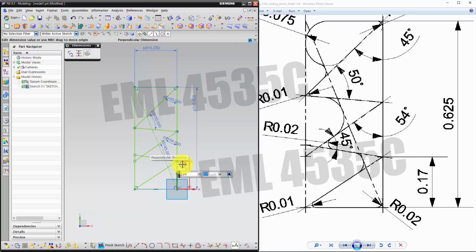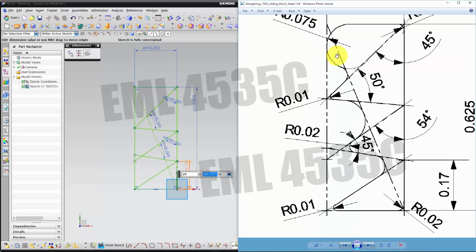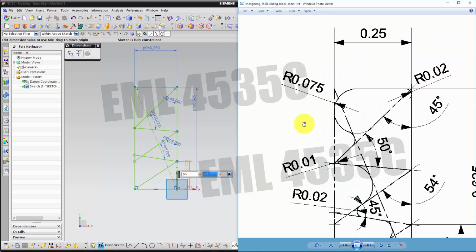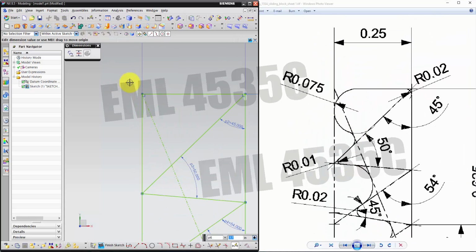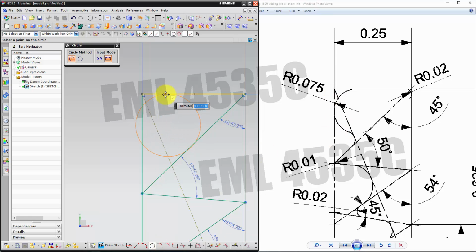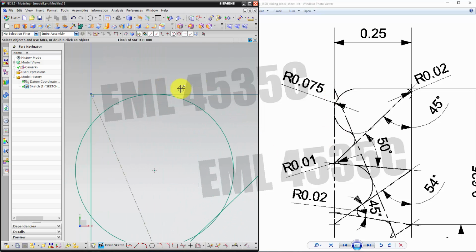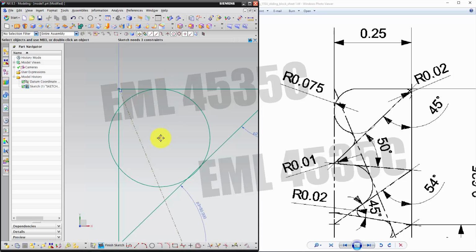Just tune my mic. Okay. Then those corners are fillets. Okay, then the top corner might be a little bit harder to use a fillet. So you can just get a random circle, and I think it's not giving me the tangent constraint, so it doesn't matter.